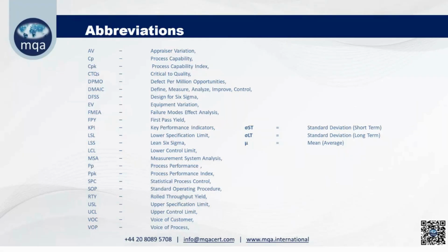Specification is a drawing requirement. If the drawing says plus minus 0.1, suppose it is 10 plus minus 0.1, then what is the upper specification limit? 10.1. What is the lower? 9.9. So specification limit is defined by the drawing tolerance.